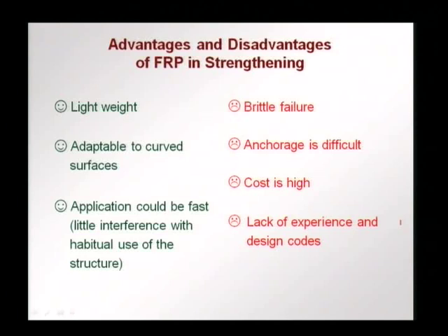The application is also fast. Some epoxies can even cure in a few hours. So, the application could be quite fast and little interference with the normal use of the structure. Say we have to repair a bridge, we cannot close down the bridge for many days. So, the application can be quite fast. So, the main advantages of FRP are lightweight, it is adaptable to curved surfaces, and we have applications that can be very fast.